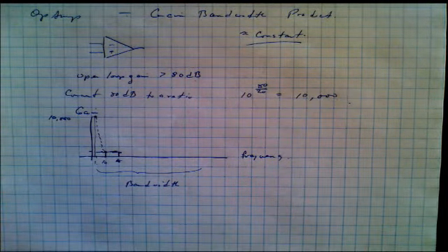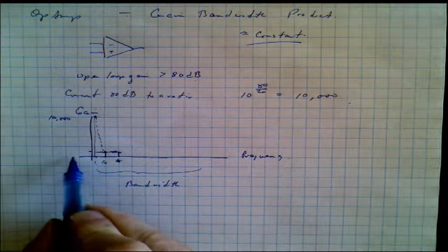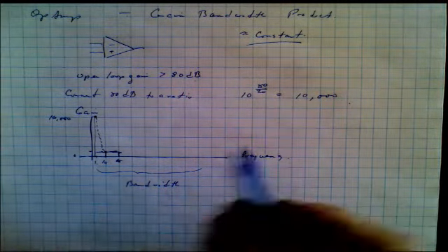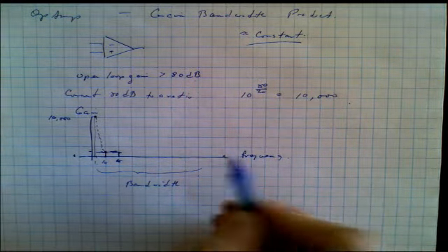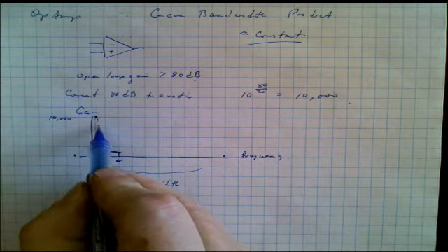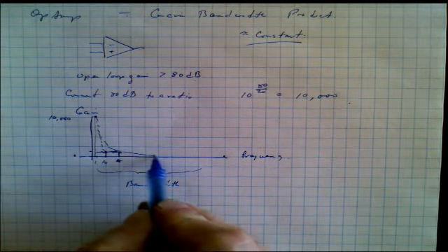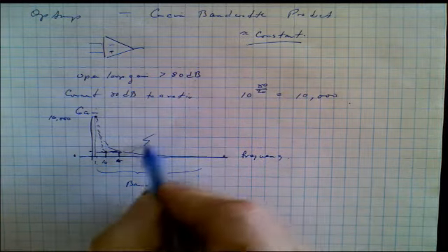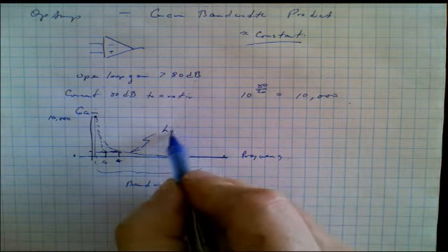So you can see what's happening is that the gain and the bandwidth curve is really, really steep like this. And if we had a gain of 1, well then the frequency would be like 10,000. So it'd be over here someplace. And so if we connected all these together, what we would get is a curve that looks like this. And this is really a hyperbola.